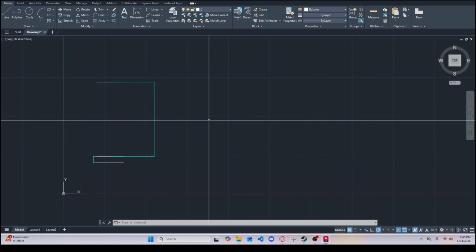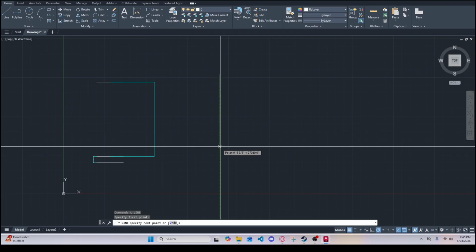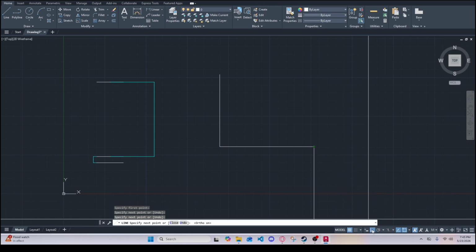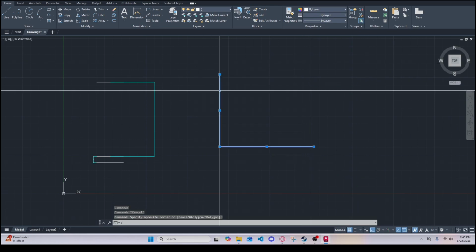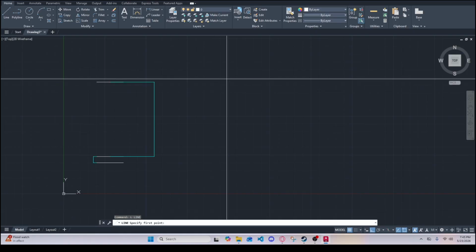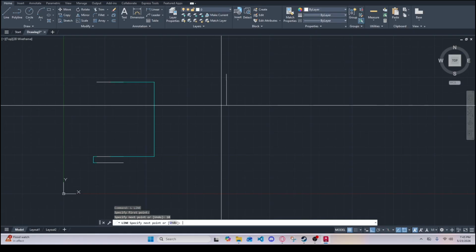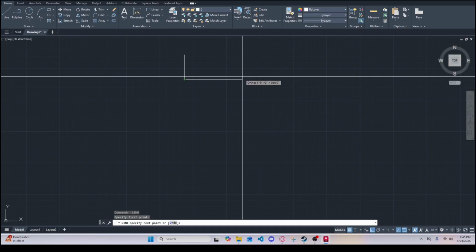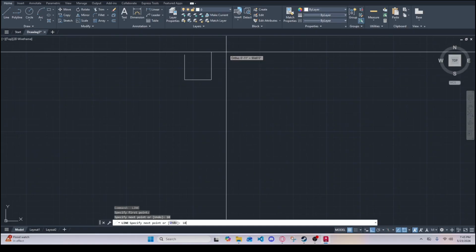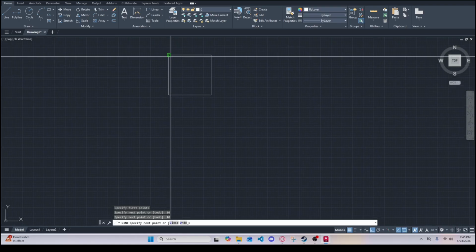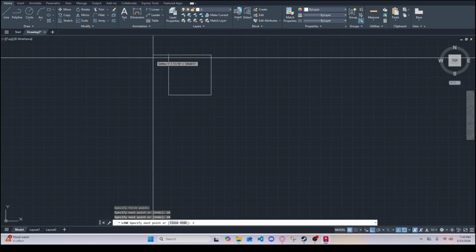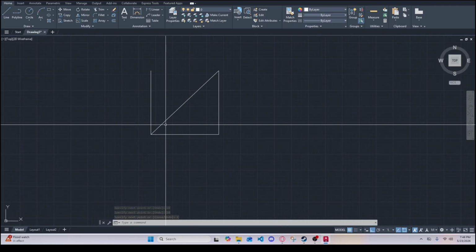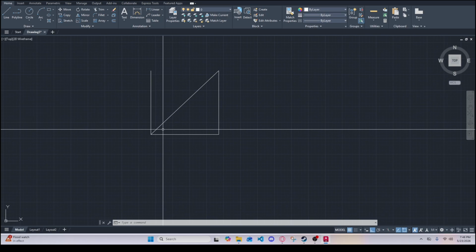Now let's say, let's draw a box. Right here, you can probably use your F8, your ortho on, just to make it simple. Let's do a 10 by 10 box. So 10 by 10 inches. So 10 inches. Oops. 10, and you can do 10 inches again, or if you just type in C and enter, it'll close up on wherever you first started off. Since I did that hiccup where I restarted again, that's where it ended.